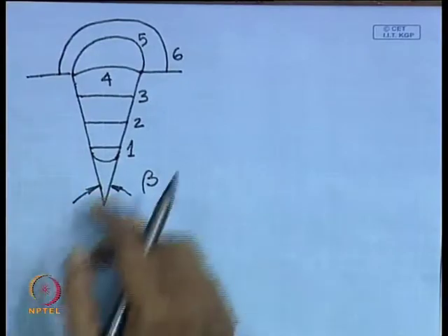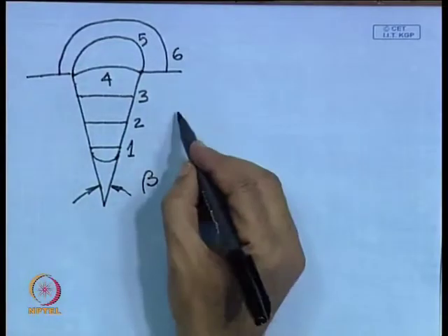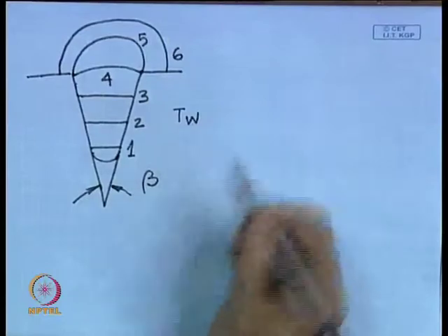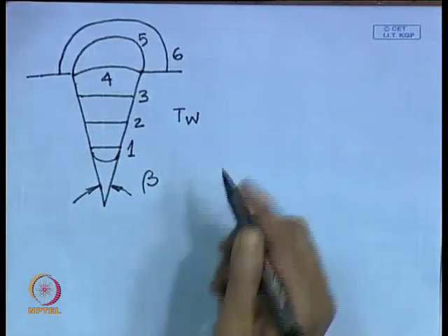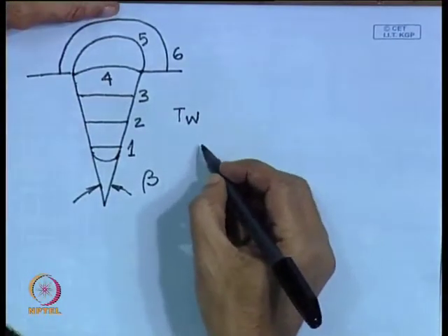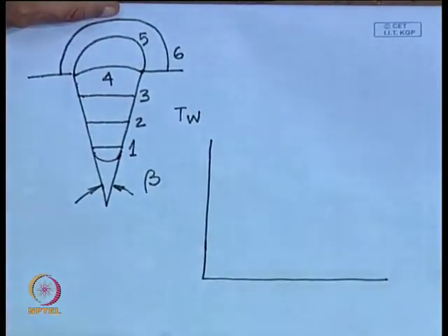And when we are doing this, how are we getting this? We are getting this with the increase of temperature. With the increase of temperature, which temperature is increasing? The solid wall temperature is increasing. Liquid temperature is more or less kept constant. So, what will happen? In essence, the degree of superheat goes on increasing. So, if I make a plot, I will have this kind of a phenomenon.